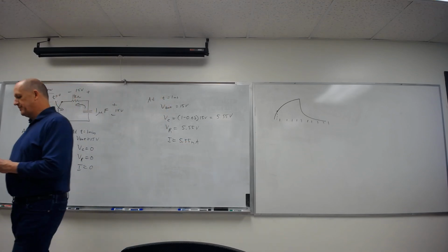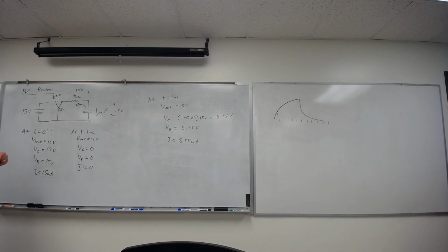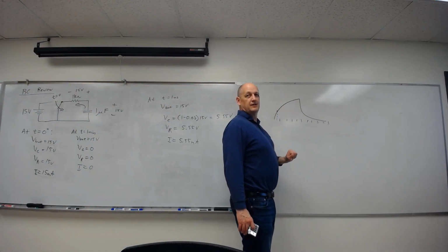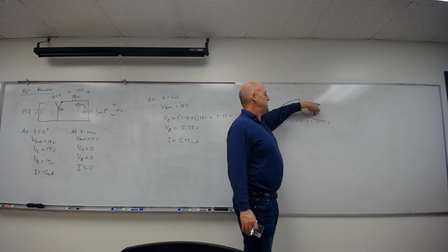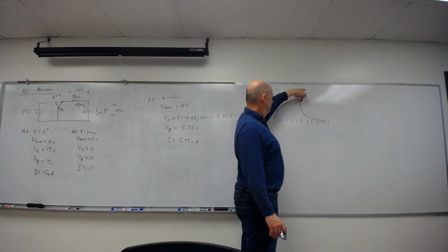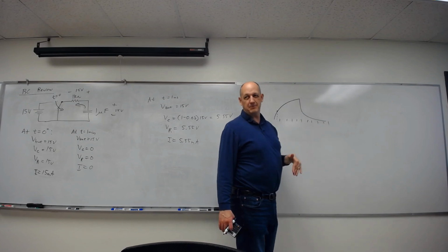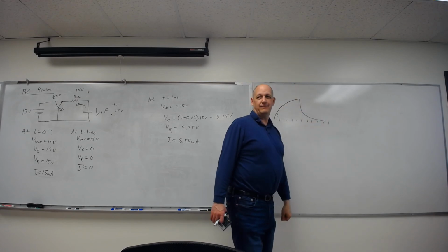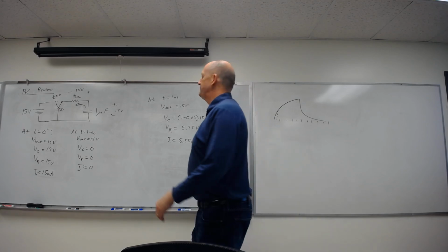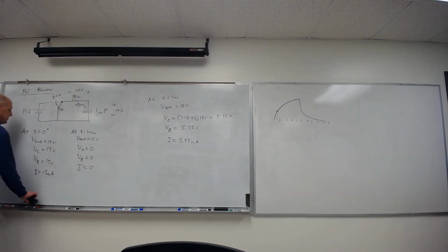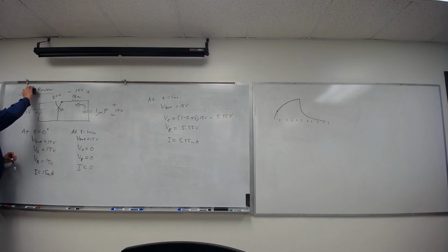So also be careful when you're charging, the capacitor voltage would be following this charging. The resistor voltage will actually be following this because it starts maximum and goes down. And the current will be following this because it starts maximum and goes down. When you're discharging, everybody's going down. Okay, we're not going to do it live, but we need to understand it.